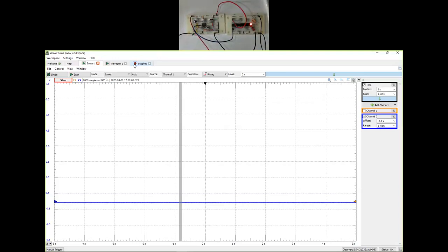So when it comes to the real test, my circuit is behaving a little bit differently as compared to how I did the fake data. So it looks like my real switch needs a bit longer pulse. So I need to increase either R1 or C1 to incorporate that aspect of the real switch.